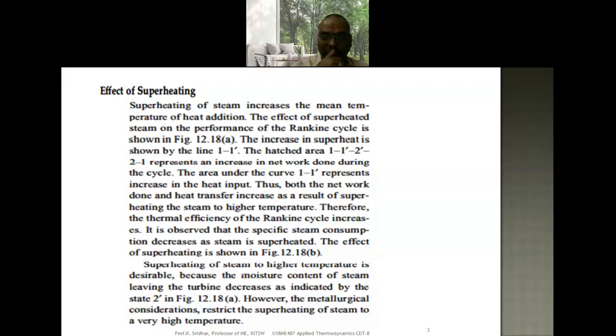So now, what is the effect of the superheating, whether it is desirable or not? So here you can see the superheating of the steam increases the mean temperature of the heat addition. That is, what is the basic effect of the superheating? It increases the mean temperature of the heat addition.